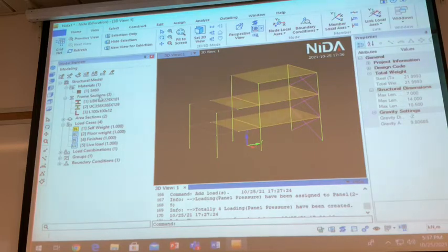The property course can help you to define the detail, section property, material property, or the job collection. Now, you have the loading. Is it enough? We have the last requirement because so far you set up the equilibrium equation, but however, this stiffness matrix is not really a structure.